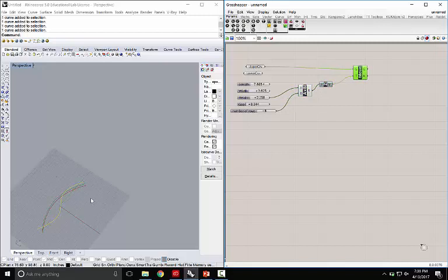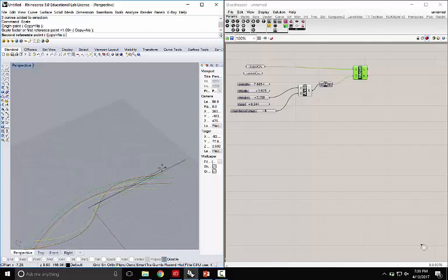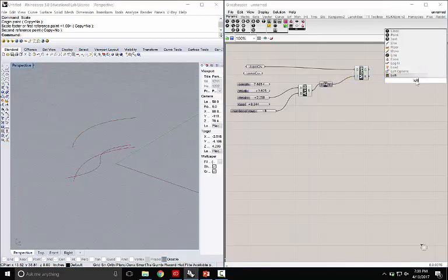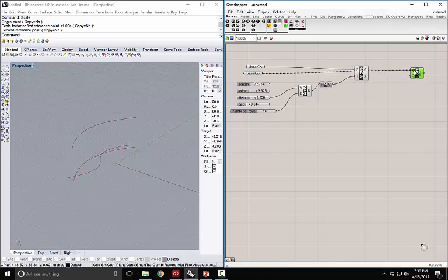And I can see right away that my curves are huge. So I'm going to just, here in Rhino, scale them so that I don't have a ton of bricks that I'm dealing with all at once. This is sort of proportionate to a wall that is 6 units high. And then we're going to loft to create the surface between these 2 components. So between the one that we just moved and then this original lower curve.